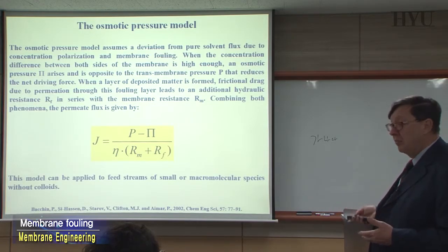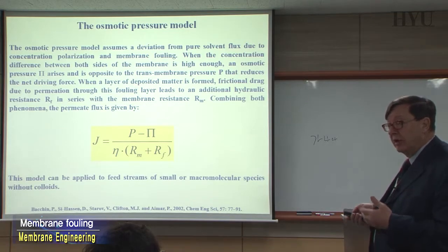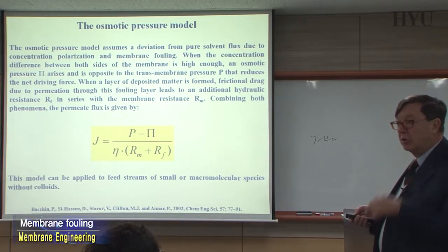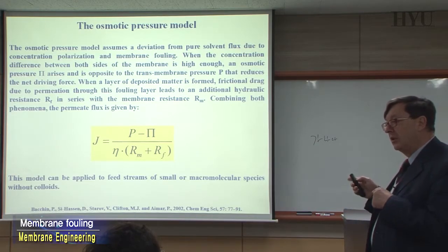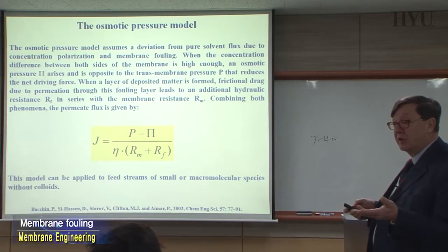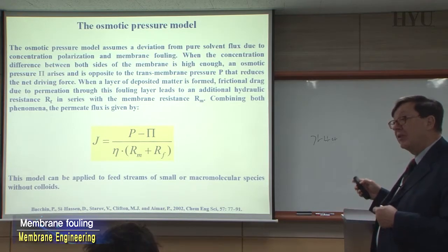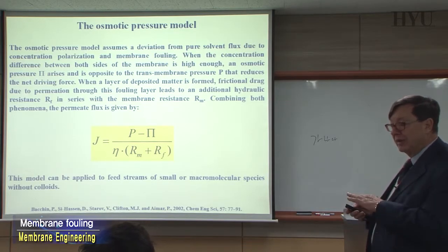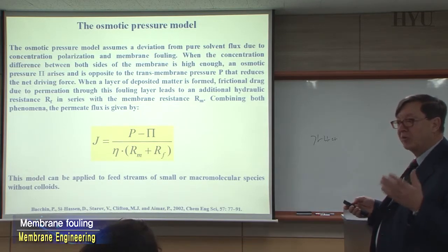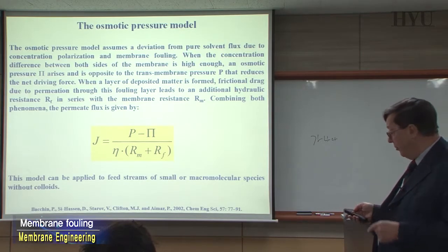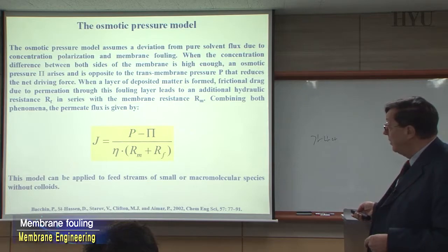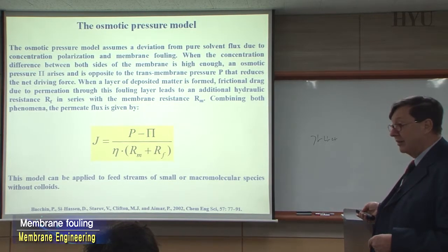These can be membranes with nanofiltration behavior, in which also some solutes of relatively low molecular weight will not go through the membranes. They will accumulate at the interface, and they will create a concentration that will give some significant osmotic pressure. So initially, with the clean membranes, no problem, no osmotic phenomena. With the fouled membranes, you have to consider the possibility of osmotic phenomena. That means the driving force is no more delta P, but is delta P minus delta pi.